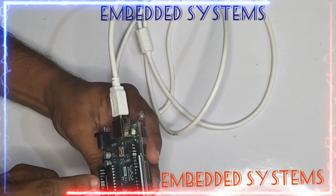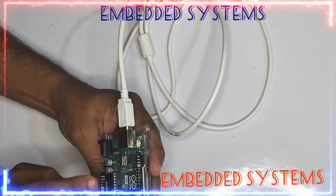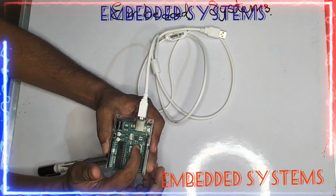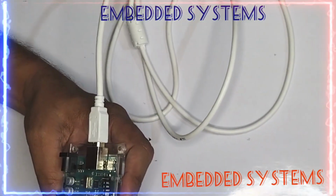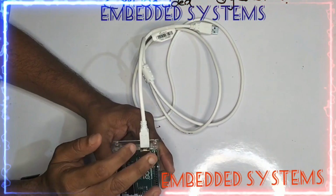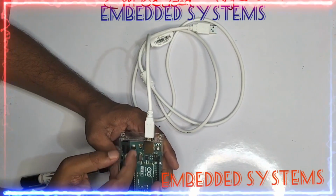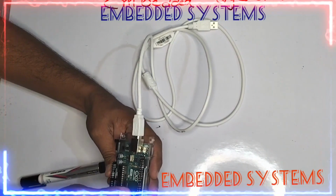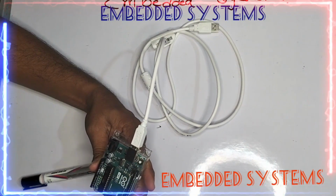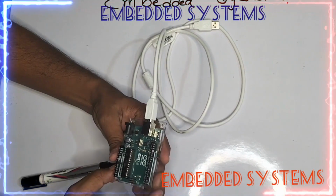And here are the power pins, friends. We can take voltage supply from here to the external world. There is also an LED connected to pin 13, which can toggle. And here is the power supply jack, which can take 7 to 12 volts. For development purposes we use the USB, and for the field we use a battery, which is connected over here, so the code burned inside will run. And this is the reset pin. If you want to reset the board, you can press it so that the code starts executing from the beginning, friends. This is the basic setup of an Arduino.